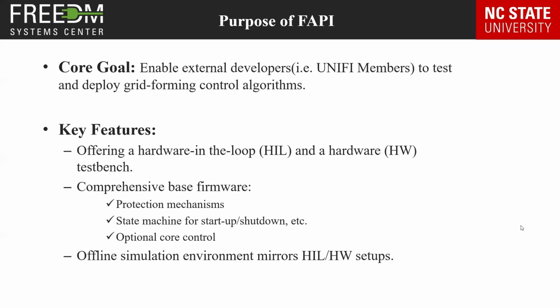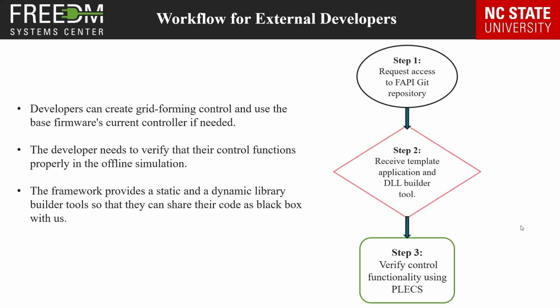The purpose of this FAPI framework is to provide the external developer an offline simulation environment which has been set up to mirror our HIL and hardware setup. To access these test facilities, an external developer will need to use the FAPI. The external developer can develop their grid forming control that may or may not include a current controller, and they can utilize the current controller in the base firmware if needed. The developer needs to verify first that their control functions properly in the offline simulation.